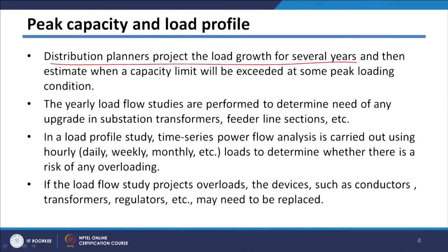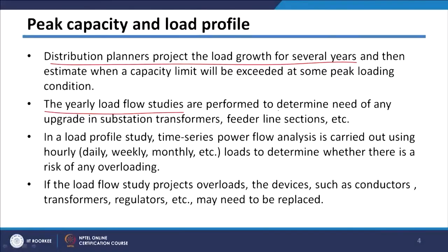In this case yearly load flow studies will be carried out. Considering the peak load condition, yearly we can calculate load flow and determine the need of any upgrade in substation transformers, feeders and line sections. So depending upon the load flow studies at peak load, we can calculate loads in various parts of the distribution network, and we can see whether any component is getting overloaded and needs some kind of replacement.